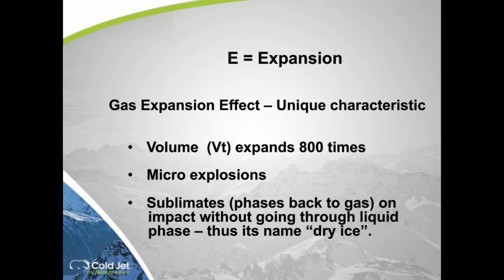So all these little micro explosions go on at the surface, and they just blow the contaminant off of whatever substrate you're cleaning. So it goes back into a gas, and it's dry, and thus the name dry ice. And that's the magic of it. The kinetic energy is common to some other blasting media, but that thermal property and this expansion property are very unique to the magic of dry ice.